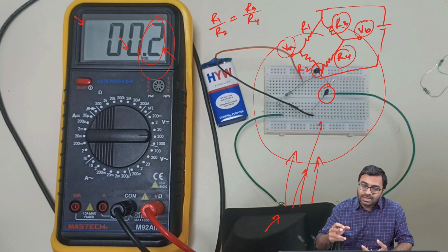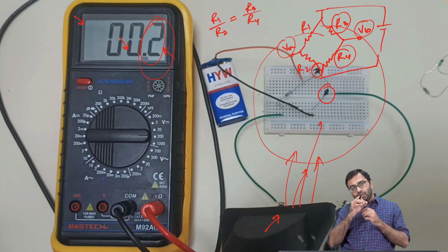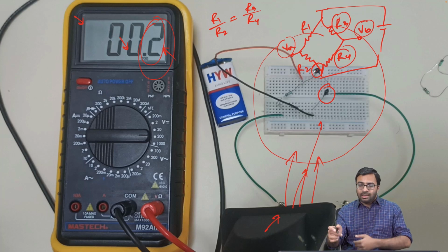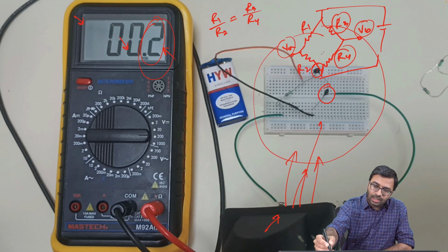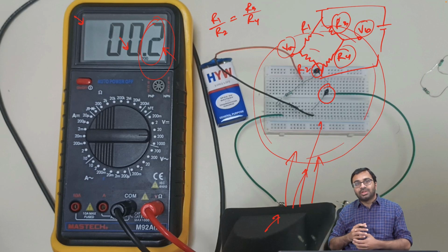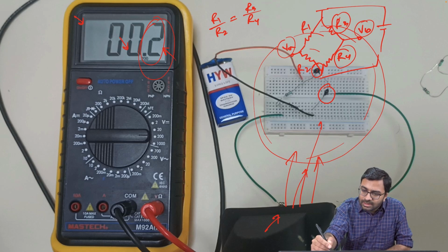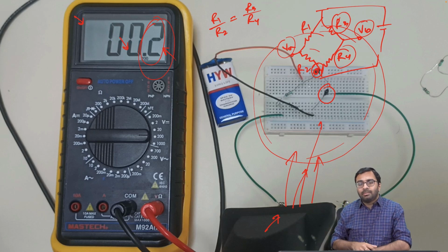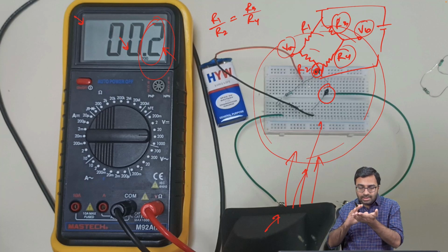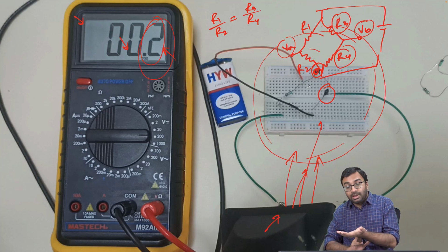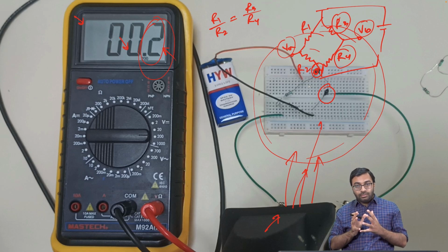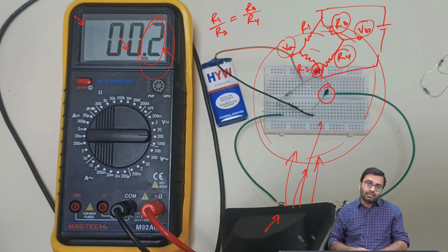But if you use only a single sensor, as we have seen in case of voltage divider circuit, and if the temperature around this sensor system changes due to any reason, that will affect your reading or measurement. For example, say in this case the entire sensor system is designed to measure body temperature. Now this sensor should measure the body temperature if you bring that sensor in touch with your body. But if the ambient temperature is also changing or if it's different, then you will get a wrong result.